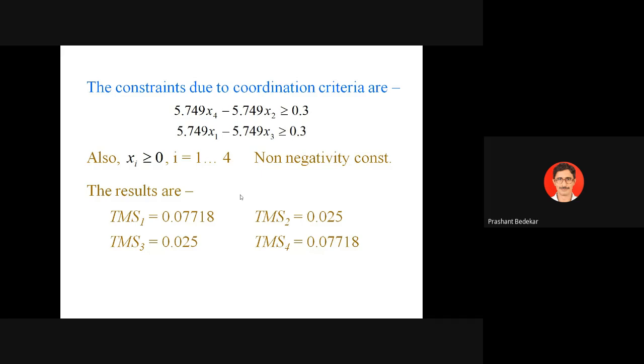If you are considering an electromechanical relay, you will have to make a special arrangement such that the time multiplier setting should acquire the value in fixed steps. It cannot be any fractional value. It can be a fractional value in fixed steps for an electromechanical relay.